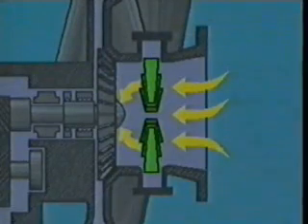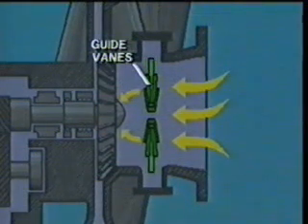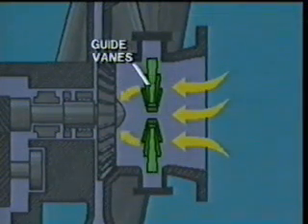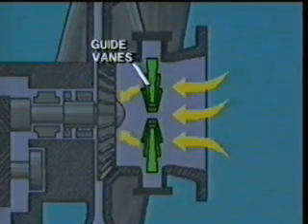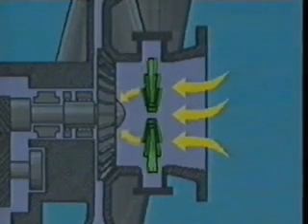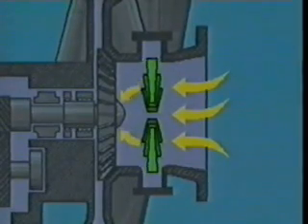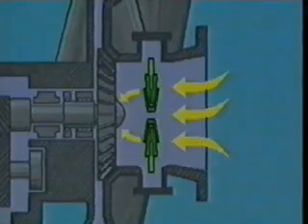To control performance in some compressors, adjustable guide vanes are installed just ahead of the impeller. These guide vanes slightly throttle the suction gas flow and pre-rotate the gas into the impeller eye. These guide vanes can either be adjusted manually or adjusted automatically with a suction pressure controller.